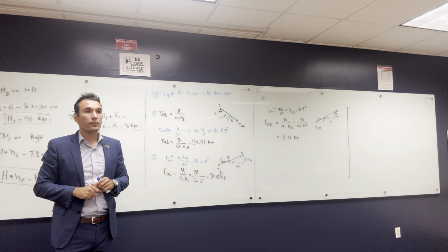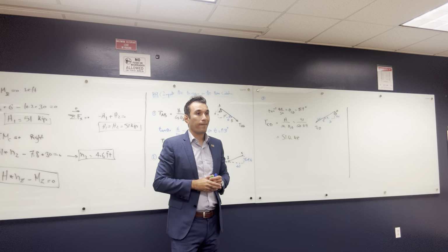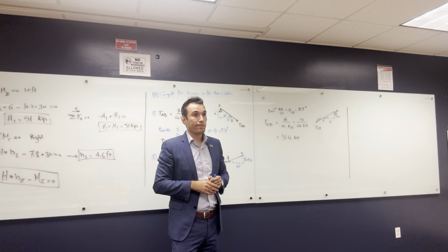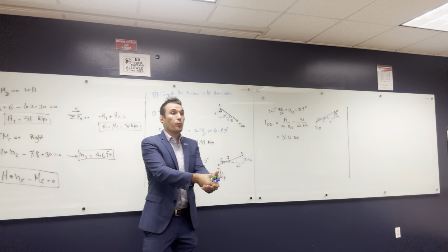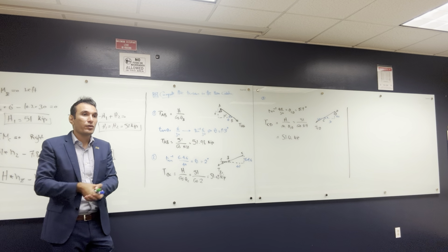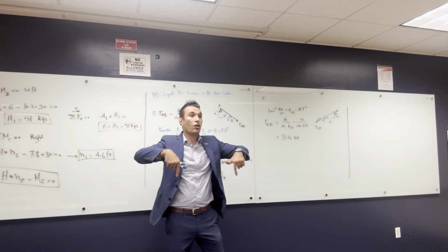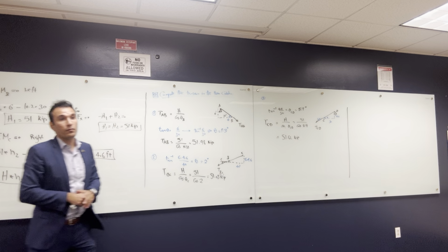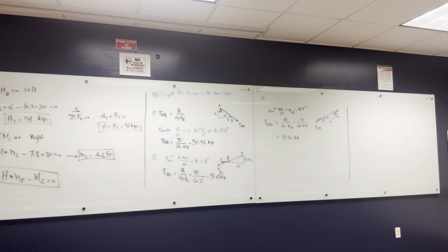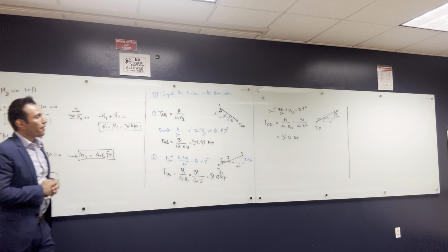Professor, when we're doing post tension cables, we have a long cable that needs to be stretched from both ends. In this case, sometimes we have a force here and a force here. How come that doesn't make the cables unstable? No, those are horizontal forces on the cable. That's reaction. That's how you anchor the cable. That's reaction, not load. All the loads on the post tension cable come from the concrete going down. You pull them so that you can make anchors, so that you can provide the stability. If you didn't pull them and left them loose, they are nothing. That's why you can make this hinge situation. Okay.